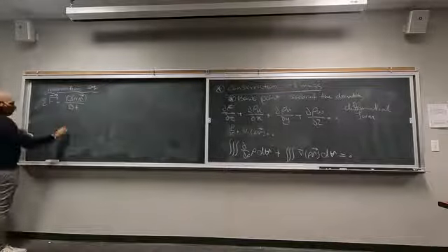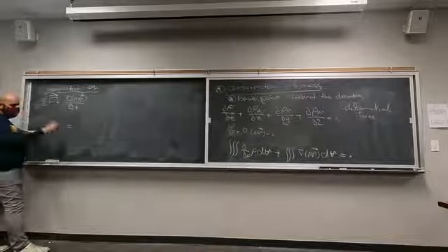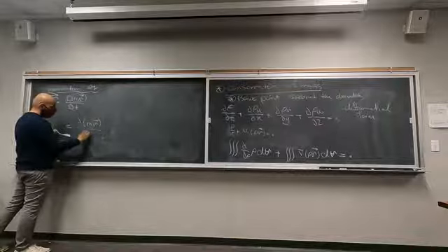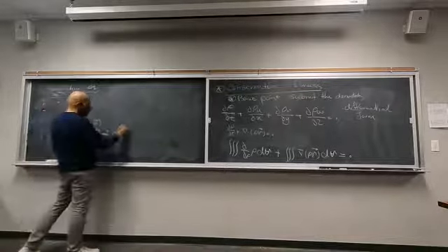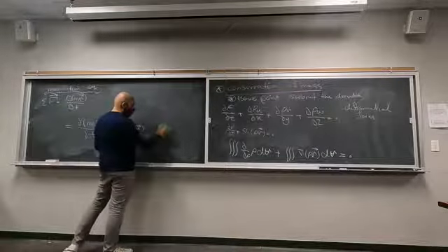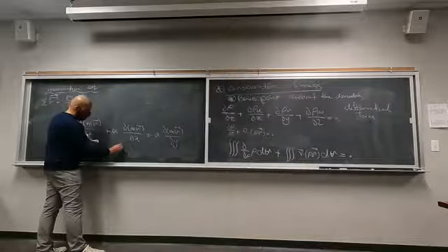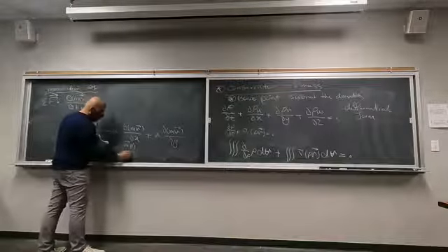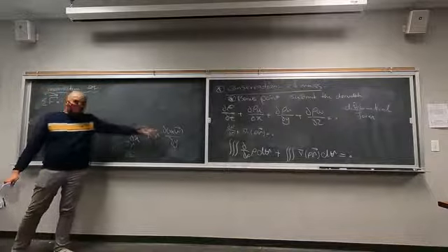Okay, so based on the definition we have had, what is going to be this total derivative with respect to time? The total derivative is always with respect to time, so it's going to be partial mV partial t, right, plus u partial mV partial x plus v partial mV partial y plus w partial mV partial z. Okay, so inside these derivatives, as you can see, we have a vector, a velocity vector.